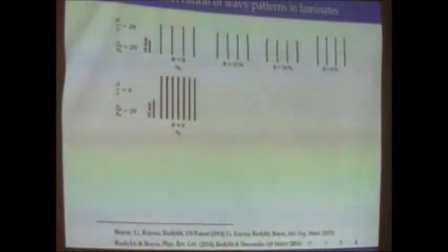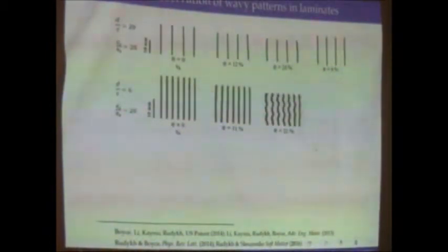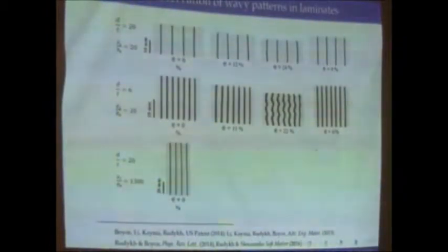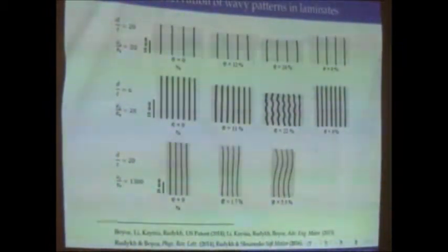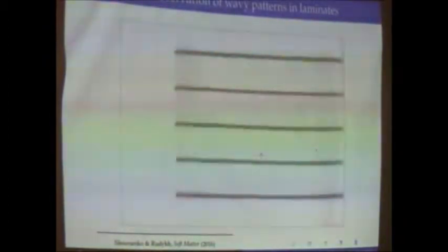So this is actually an experimental picture, which also might not really look like that, of a 3D printed layered material. Again, I compress it in the direction of the layers and expect it to buckle. That indeed is what happens. We can print different volume fractions of these phases and obtain different wavelengths, and we can also print different materials and go straight to long wave type of instability. So this just illustrates that it's something we've actually done experimentally.